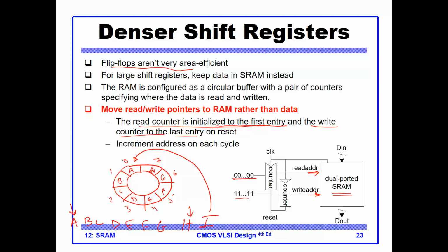Now, be careful that you will have meaningful data coming out only whenever you complete populating, meaning completely writing data to the circular FIFO, and then the data will come out meaningful. But before you populate it, it will not. So you will need 7 cycles.